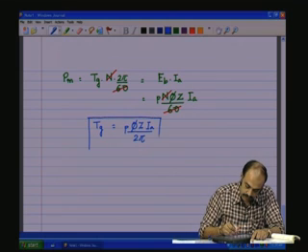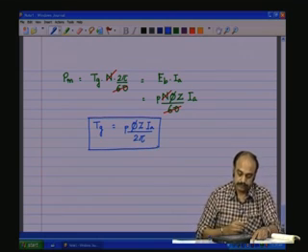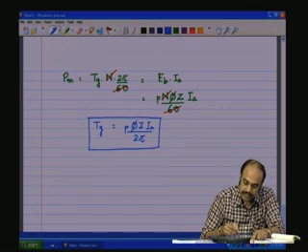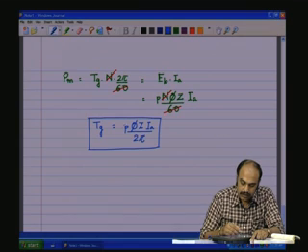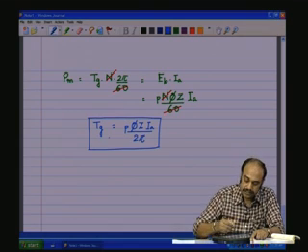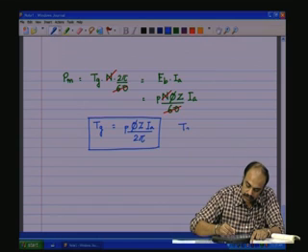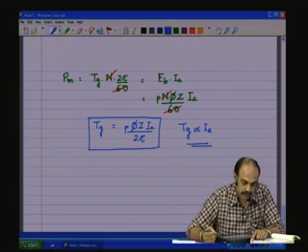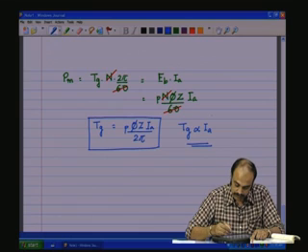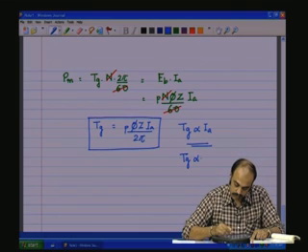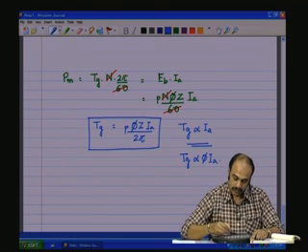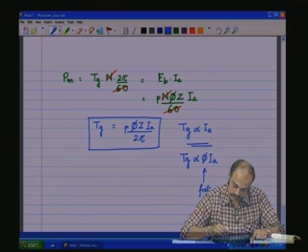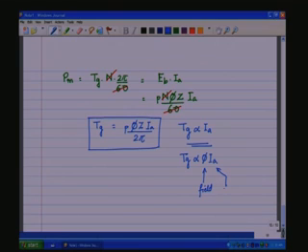This is the equation. So, you see that number of pole pairs, phi, z and 2 pi of course is a constant. All these are dependent on the machine parameters, and for a given machine Tg will be proportional to Ia, and also of course the flux, if the flux is constant. Otherwise, we could say Tg is proportional to flux into Ia. So, this is the field and this is the armature current or the load component of the torque. So, this is the field, the flux component of the torque, load component of the torque.